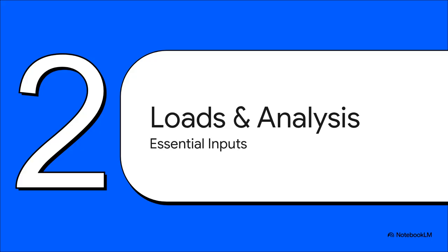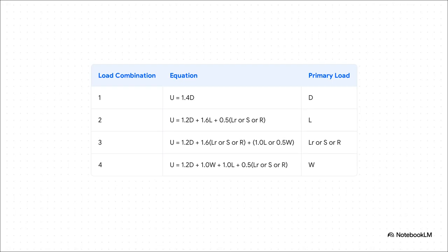What forces is this thing going to have to resist? We have to account for everything: the structure's own weight, the people walking on it, furniture, snow, wind, you name it. And to be safe, we don't just design for the expected loads. Nope. We design for the worst-case scenario.